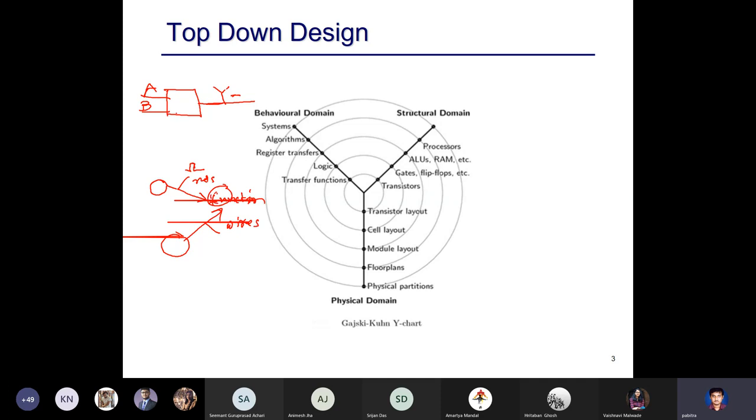Now these functions, these blocks, they can either be standard blocks like AND, which are called standard cells, for which any gates are standard cells for which the exact layout we know that they are in the library, or these can be user defined blocks where you define in terms of either a truth table or a connection of gates, a circuit built out of gates, and so on.